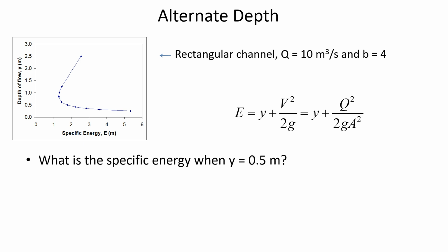So you'll remember when we were in closed conduit flow, we talked about energy sometimes with units of length, right? We talked about how much head there is, like the pressure head. We measured the amount of energy in units of length. Here, this is a measurement of energy with a unit of length. And some of the energy is the depth, but in this case, most of the energy exists as kinetic energy.